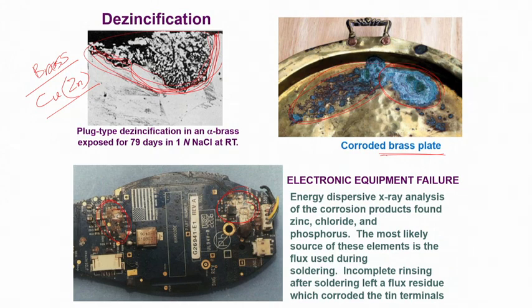So it will immediately dissolve some of the metals around, and as a result the composition of the wires and interconnects will change. And more importantly, it also allows easy electron flow even when the circuit is not on. So in other words, because of the presence of moisture or any other form of corrosive attack, it can undergo very slow but definite dissolution, and as a result there could be corrosion damage, and then eventually